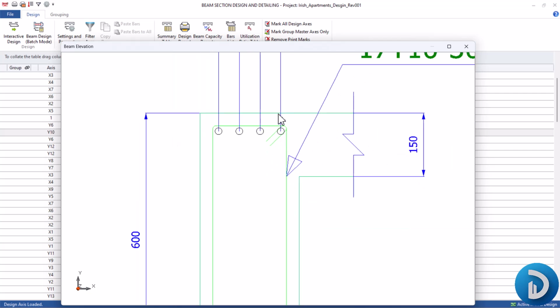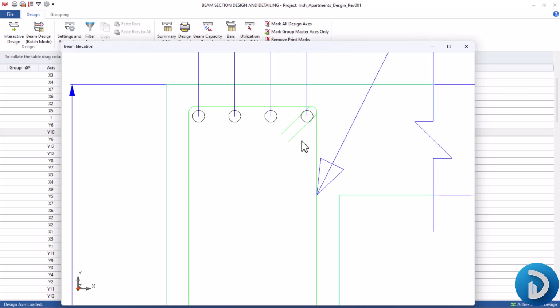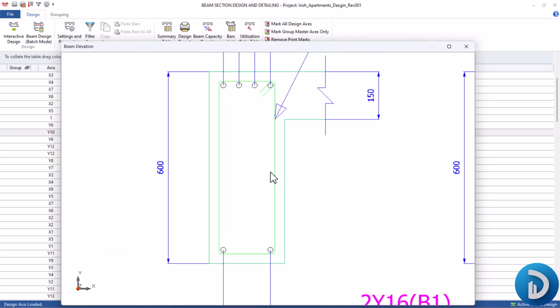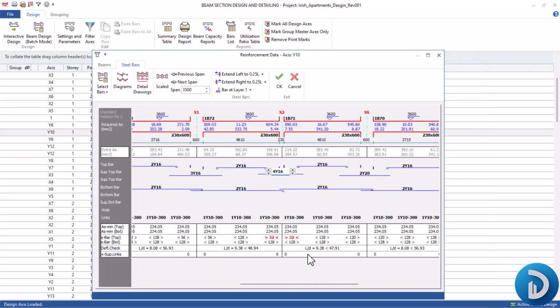And this coarse aggregate size, you also have to give it some allowance, because not all the coarse aggregate size will be 20 millimeter, some will get to 21, some 20. So it's always advisable to keep the spaces between your reinforcement as a maximum of 25 millimeter. Okay, so that it will accept that coarse aggregate, and in turn it will not cause honeycomb on your structure. So let's close this, and you can observe the spacing between the reinforcement at this top zone to be 35 millimeter.